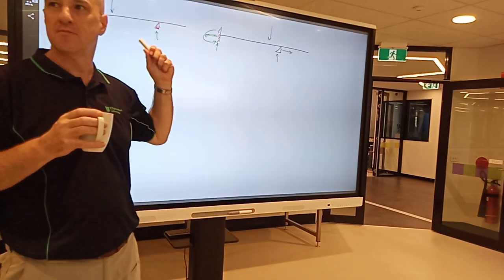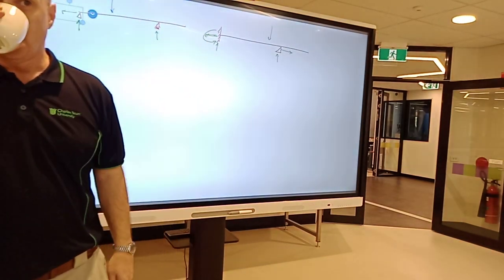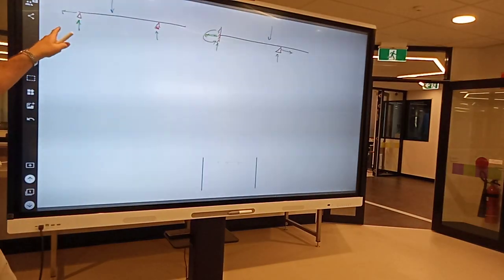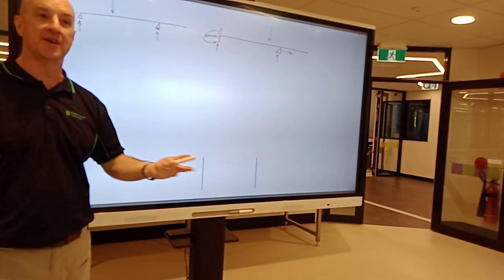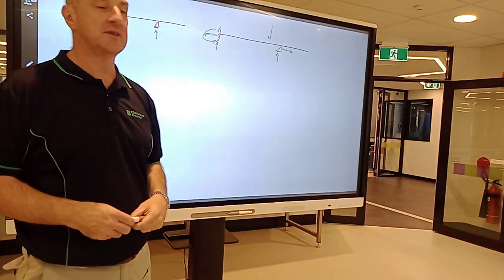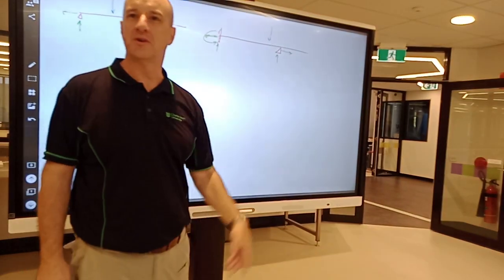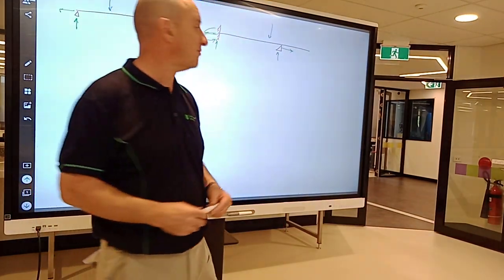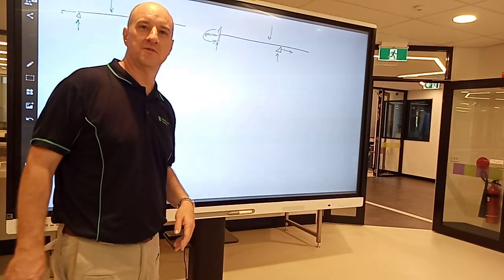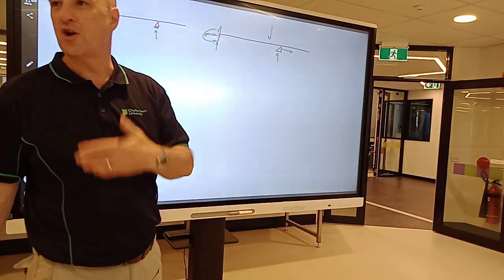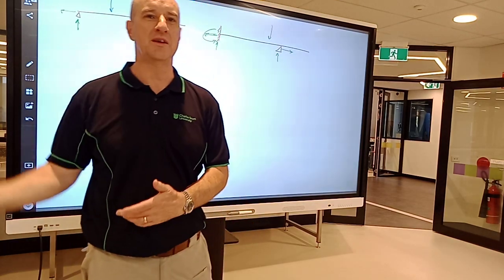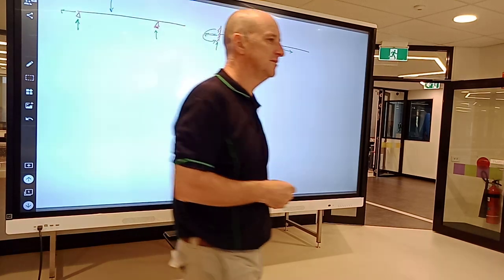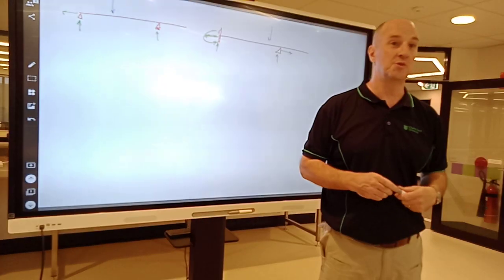Does that make sense? So, statically determinate means you look at it and you go, I can solve all that, and you go ahead and you solve it all. Happy days. And if you work out that you just can't solve it all because there's too many unknowns, then you might be dealing with a statically indeterminate beam. Okay? That's obviously the hacker's way to work it out. In the topic you do, there's a formula of this many members versus this many of those things, and honestly it looks like a confusing way to me to work it out.